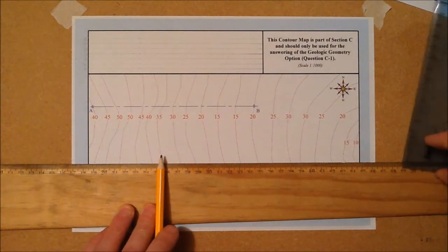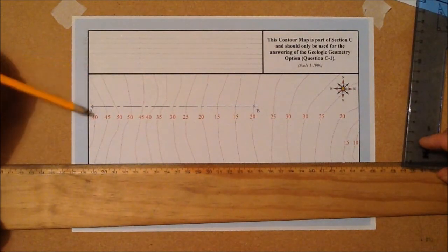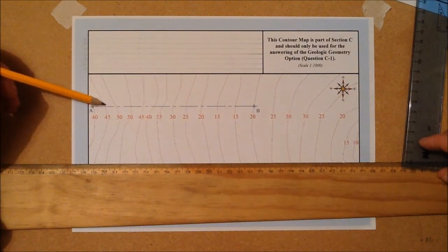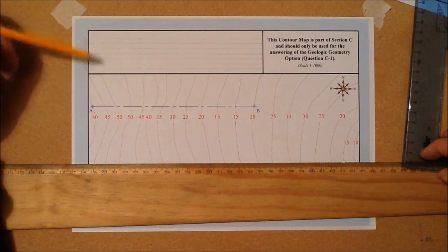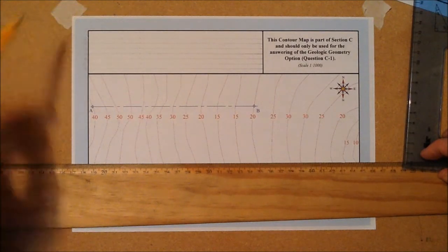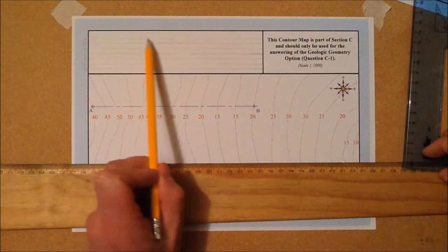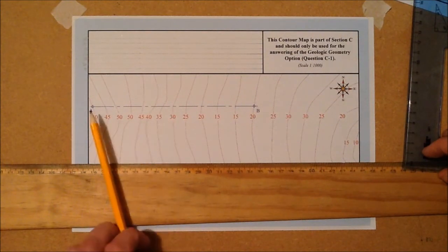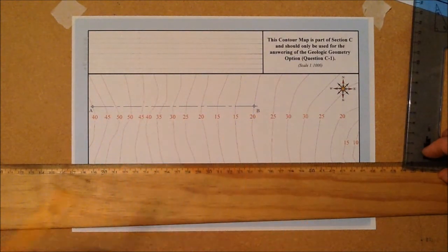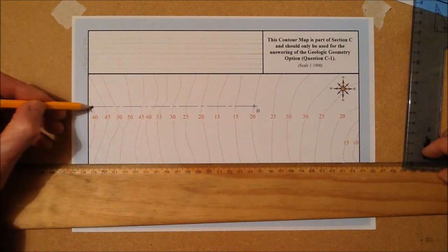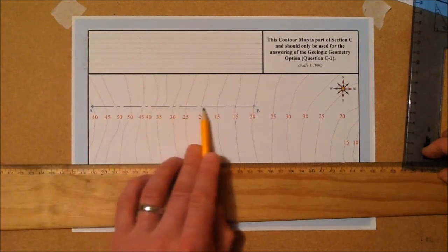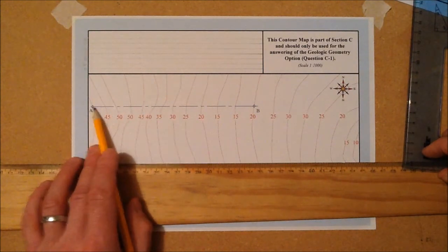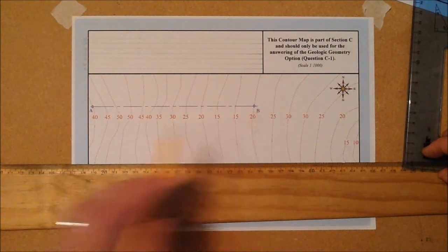Next, we have to identify and determine at what height these contours are going to appear on this vertical section. Basically what we're looking for is the profile of the hill if you were to look at it in this direction of the pencil along this line. So I'm going to bring up the points on this line AB where the contours intersect that line, right across from point A to point B.